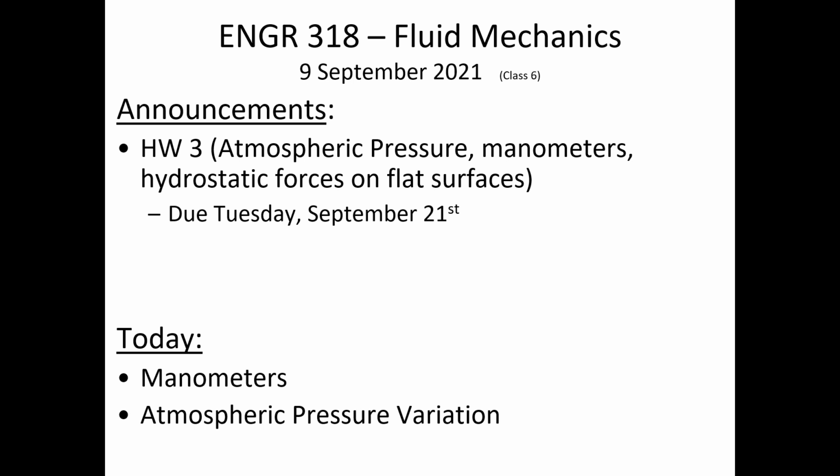And it is measuring the pressure in the pipe because there's delta H involved. And even though water's flowing through the pipe, water is not flowing inside of this vertical piezometer. Inside the piezometer, conditions are static, meaning the water isn't flowing. The water rose to a certain level, and then it stopped.